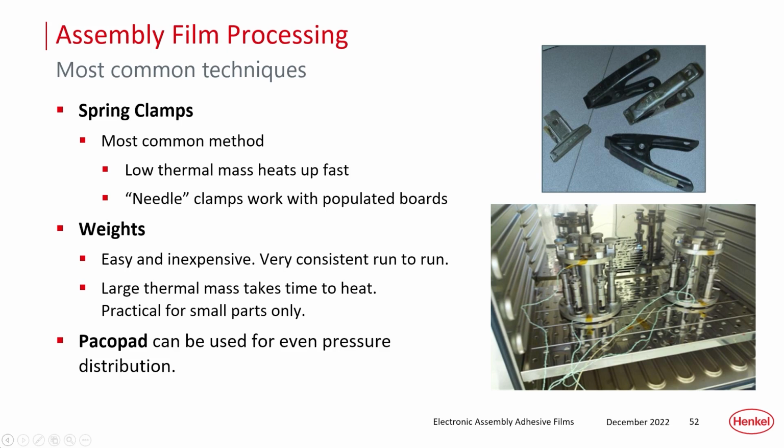Some quick pictures here of the sorts of ways that that pressure can be applied. One's with a simple heated press. Very, very simple if you've got a simple configuration of component. On the next one, you could use spring clamps, a very simple but effective system. You could use weights, which takes a bit of time to warm up during cure, so take that into account. But if they're designed properly, they'll apply a very uniform pressure, especially if you've got conformal layers built in as well to even out the pressure. And on to the next one.